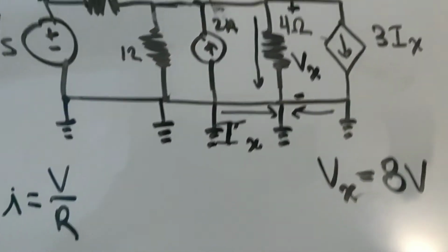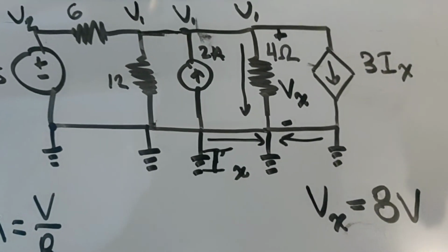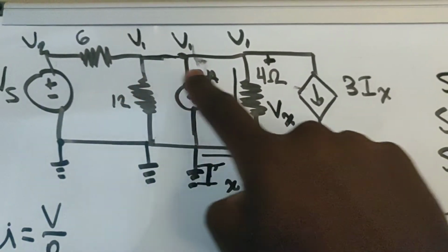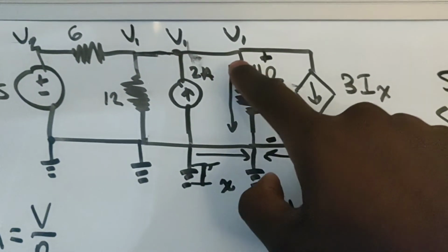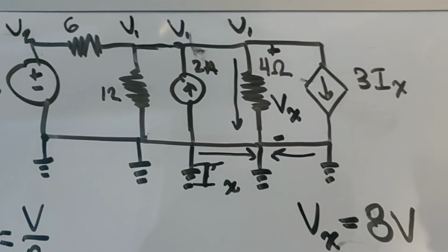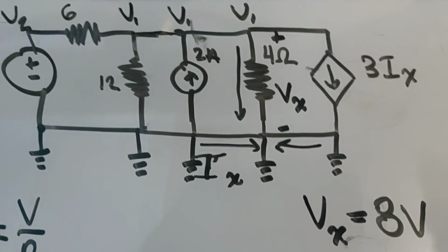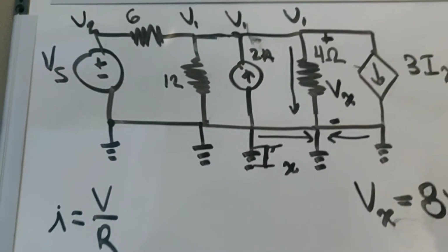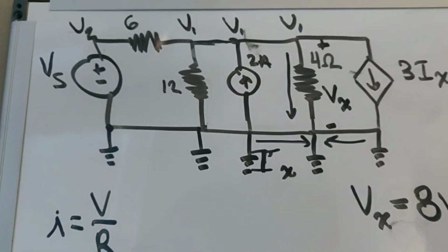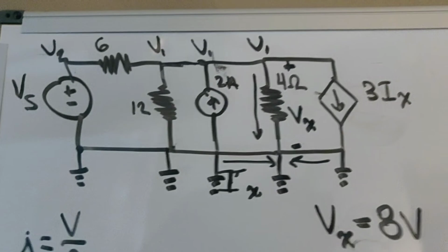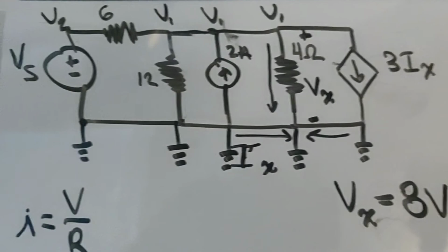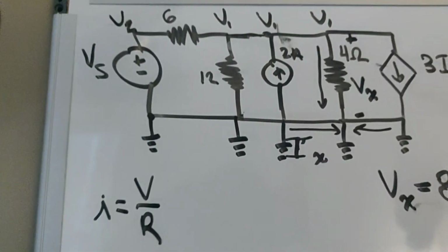If we look back at our circuit, and we take some time to really think about what's going on with this node up here, we don't know what it is, but how can we figure out what it is? It's quite simple. If you remember the principles of voltage across parallel branches, then you would know that voltage across adjacent parallel branches are all equal.